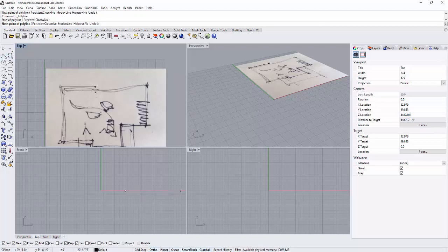If you haven't figured out yet, I am fairly new to Rhino. Used it quite a bit several years ago, but I'm just now sort of getting into it. So there was a left click on the corner here. I typed in 70 feet. That locks my distance to 70 feet no matter where I point my cursor.